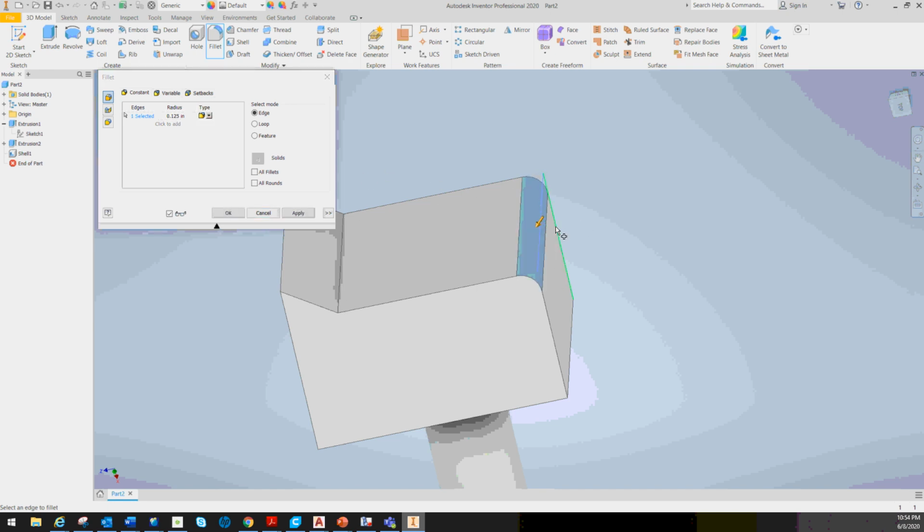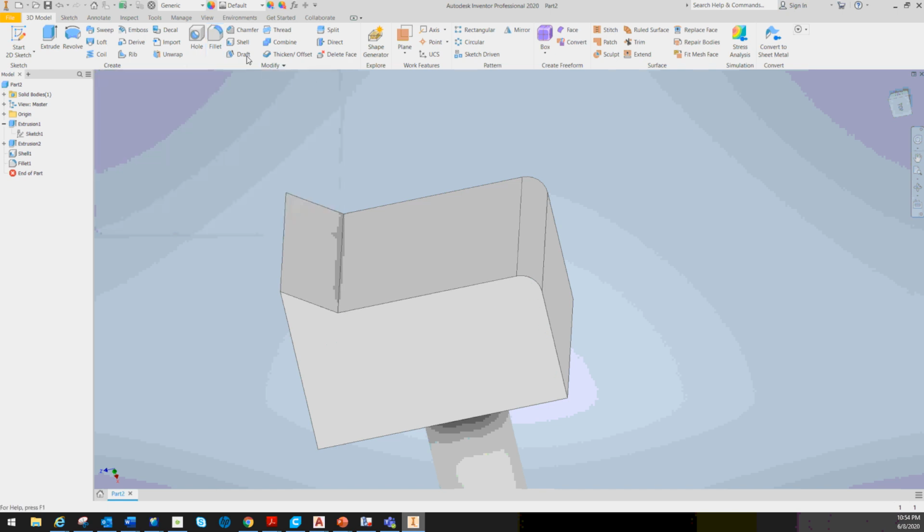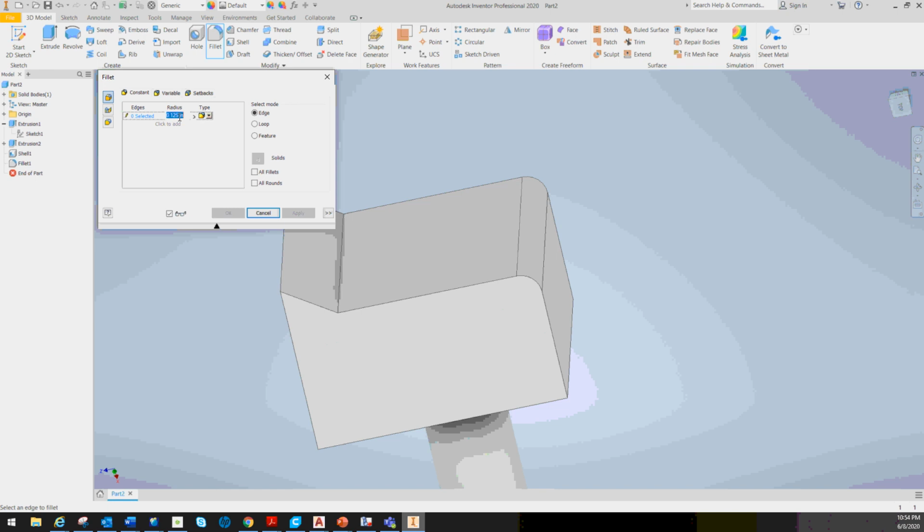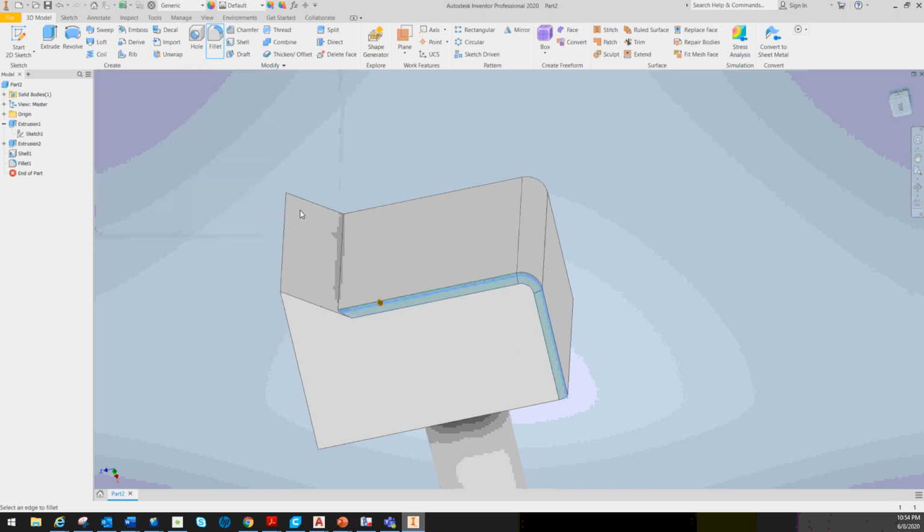We're just going to click on this corner here, and if we like that distance, we can keep it, and we'll just hit apply. Now maybe we want to select another fillet, and maybe we want to change our radius to 0.05. We want just a slight round, and maybe that's going to be on this corner right here, and then we hit apply.